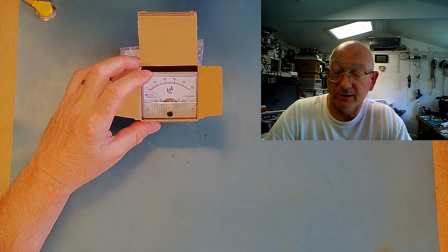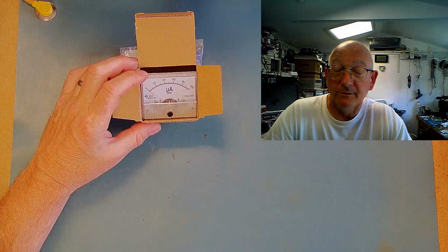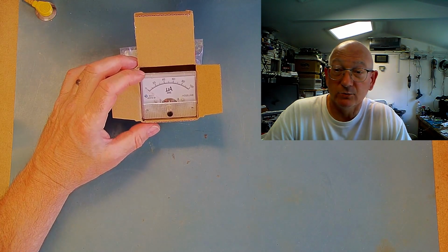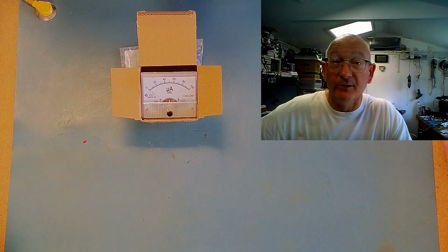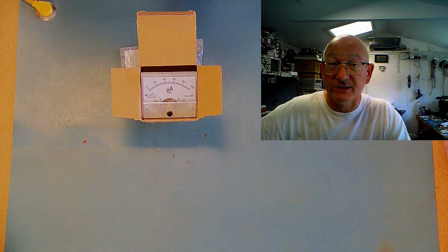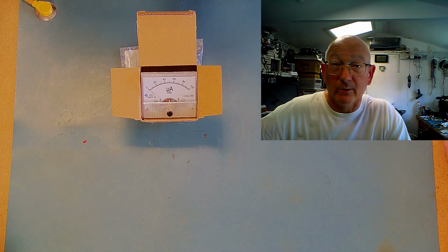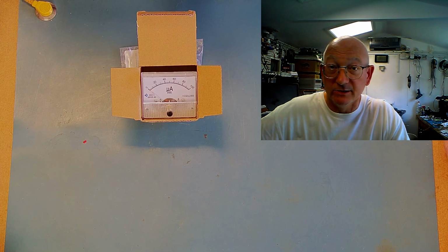In this video, I'm going to attempt to design and build an auto-ranging analog meter using this guy here. And the basic idea is to have this auto-ranging in 4 different ranges. At this point, those 4 ranges I anticipate being 100 microamps, 1 milliamp, 10 milliamps and 100 milliamps. But as I haven't actually designed the meter yet or even really thought about the concept, that may well change.